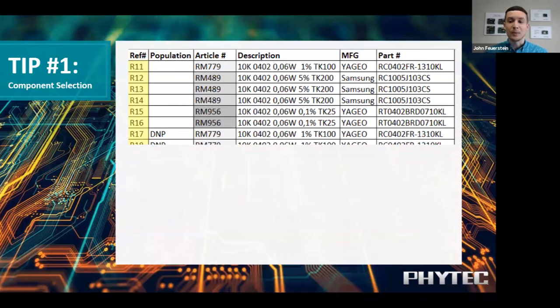It also creates more opportunities for PCN and life cycle issues to come up, right? If you have 5 different parts from 5 different manufacturers, one of those might go EOL, whereas if you just had one part from one manufacturer that you vetted ahead of time, it's going to be a lot easier to manage and less overhead for you in the long run. So it's a good idea to do these design reviews after finishing your schematic and before moving on to layout, and sort your BOM and look for parts that you could consolidate.